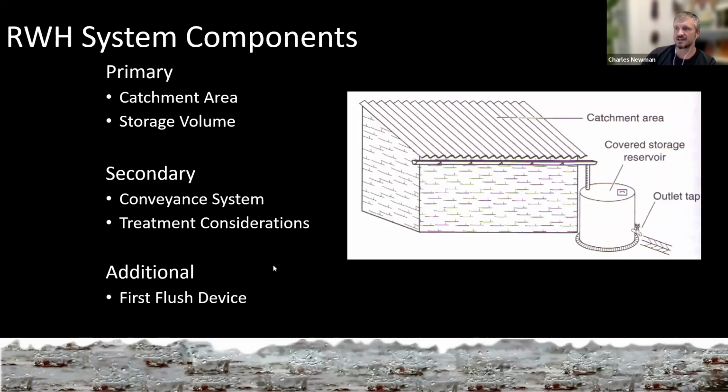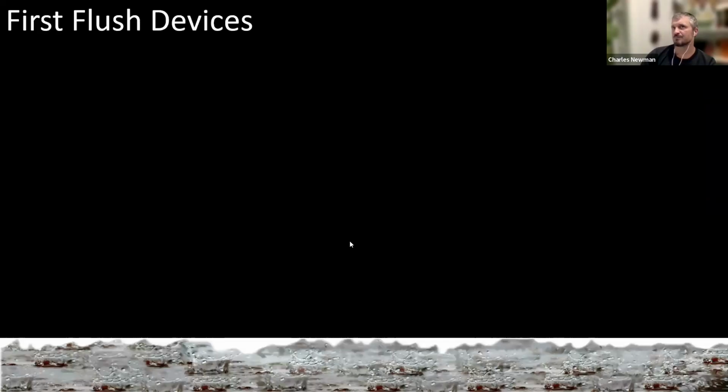This is a sort of contraption that you can design into your water catchment system that diverts a first flow of rainwater away from your reservoir. Okay, so why would you want to do that? With any roof, you're going to have leaves, dust, dirt, maybe animal droppings that you're just not going to want going directly into your water tank.